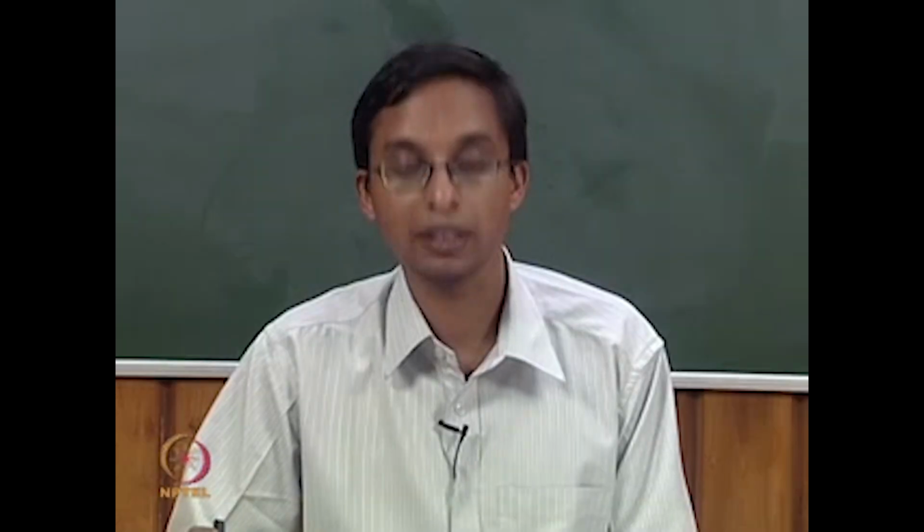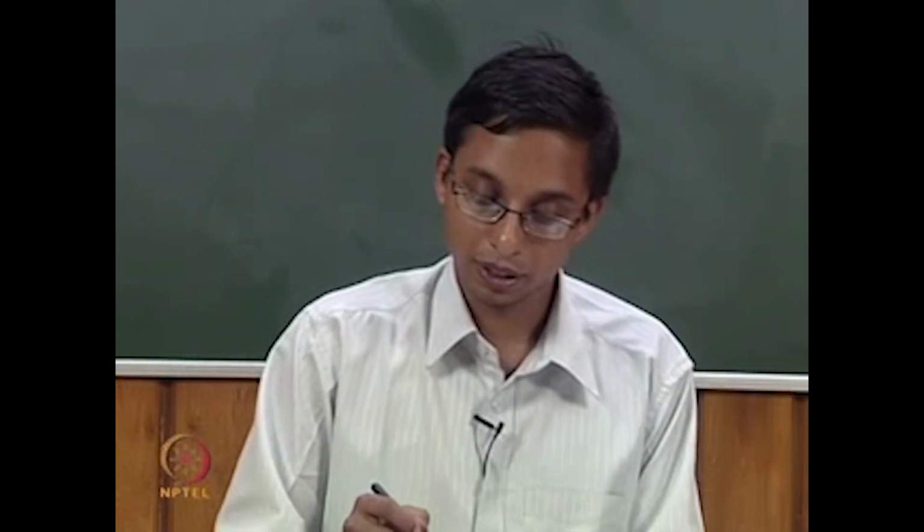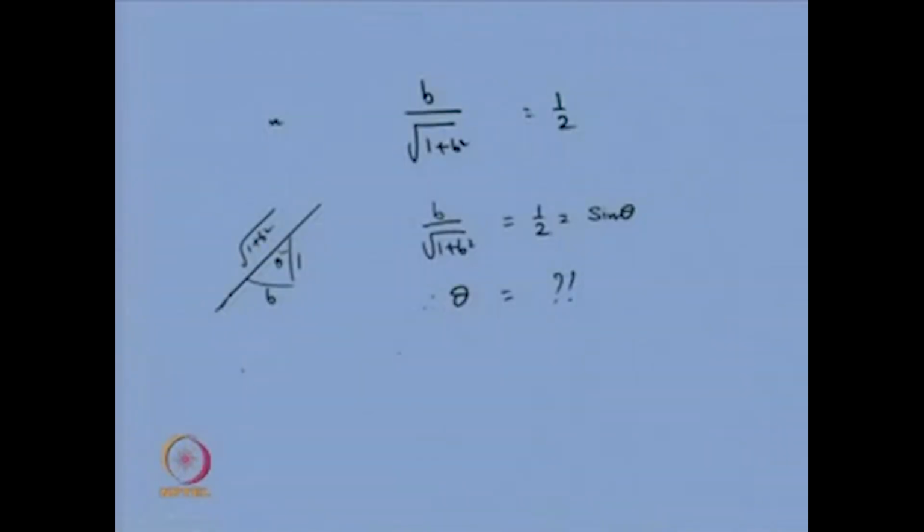Therefore, what is theta? It is quite obvious to you, so I am not going to discuss further. So, if this is so and so value, it is now quite confirmed that the best trapezoidal section, the hydraulically efficient section, will be half of a hexagon.